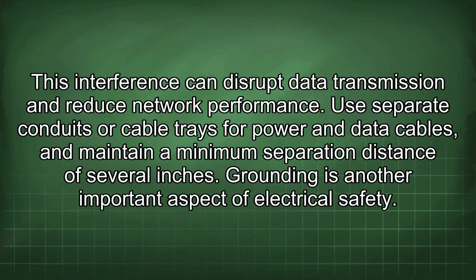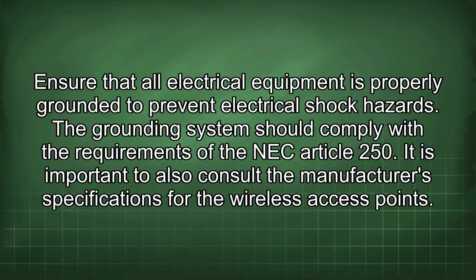Grounding is another important aspect of electrical safety. Ensure that all electrical equipment is properly grounded to prevent electrical shock hazards. The grounding system should comply with the requirements of the NEC Article 250.